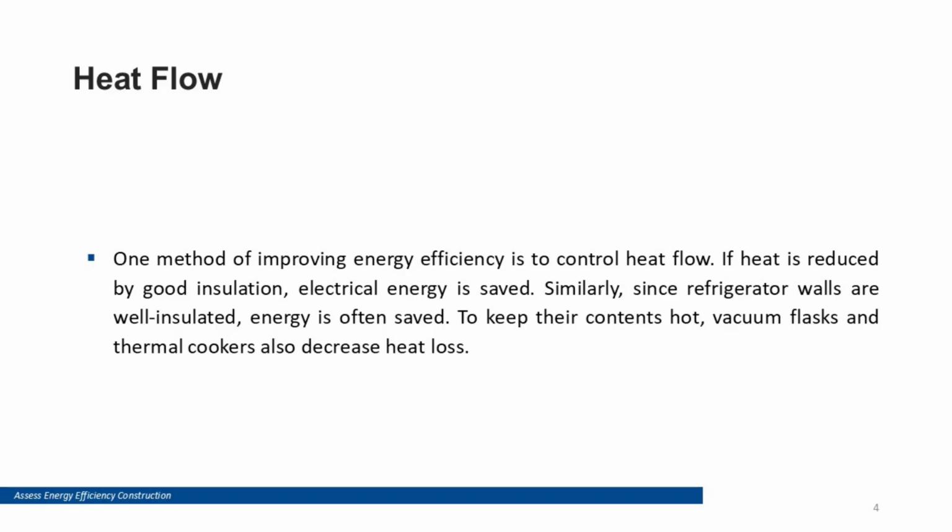Heat flow. Heat moves from warm to cold. Insulation slows heat transfer, but only if installed correctly. Gaps, compression, and thermal bridging reduce real performance. Good detailing around slabs, roofs, and openings helps maintain a continuous thermal barrier and stabilizes internal temperature.